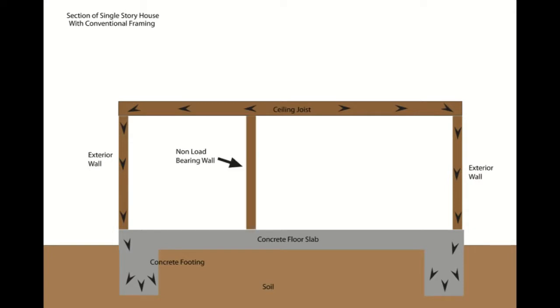Now here's a picture of a non-bearing wall. Now don't be confused, just because the weight is being distributed around this wall, it is not going through it, that it's a wall you can actually remove. It could actually be another structural member of the home, and this is where I think a lot of homeowners and do-it-yourselfers get confused. They say, hey, I'm allowed to remove this wall, and they cut into it, and all of a sudden they remove the wall, and their building starts to lean. And I've seen that before. It's not going to be a good thing.